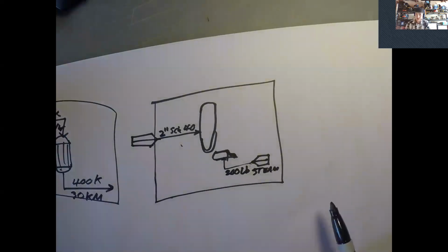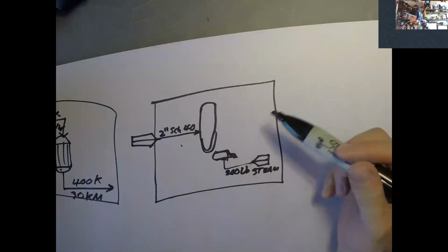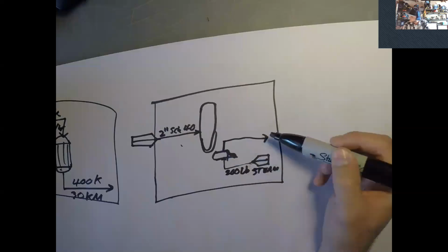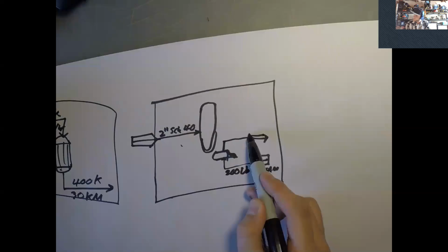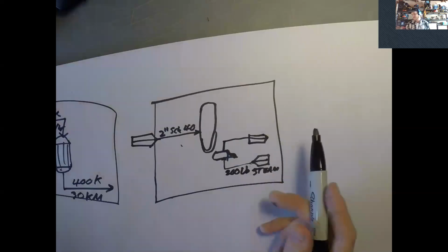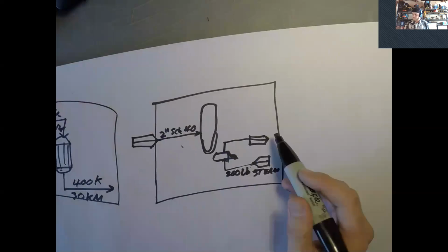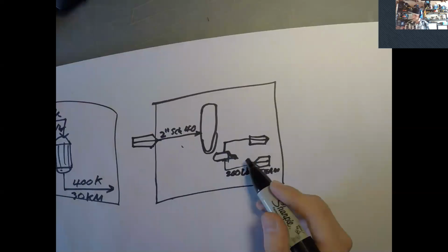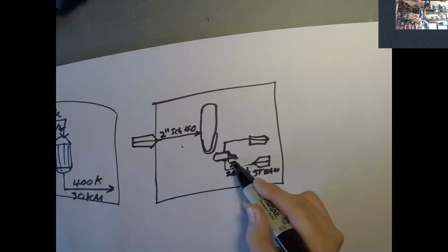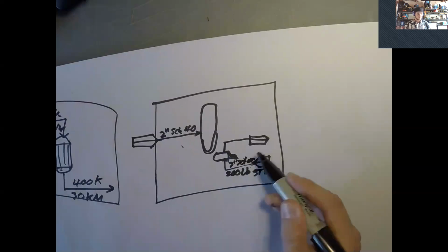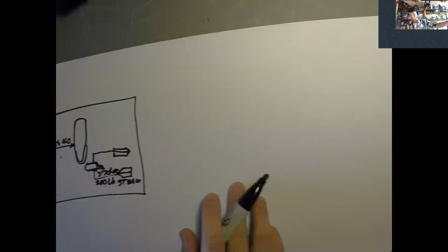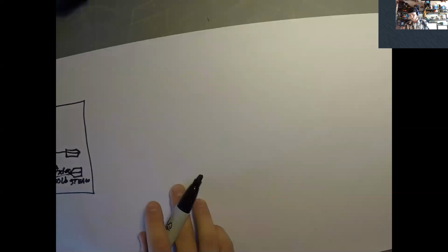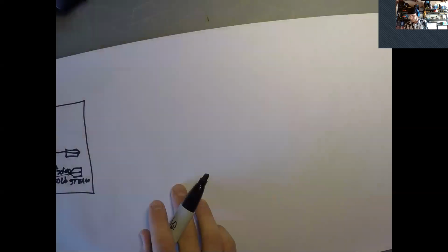Usually they call out the pressure of the steam as the spec rather than like temperature when it's being used in this type of capacity. And then it'll have a return going somewhere that's referenced. And this line would also have some spec on it, like 3-inch schedule 40. I don't know if that's even reasonable. So that's kind of how you call out your piping.